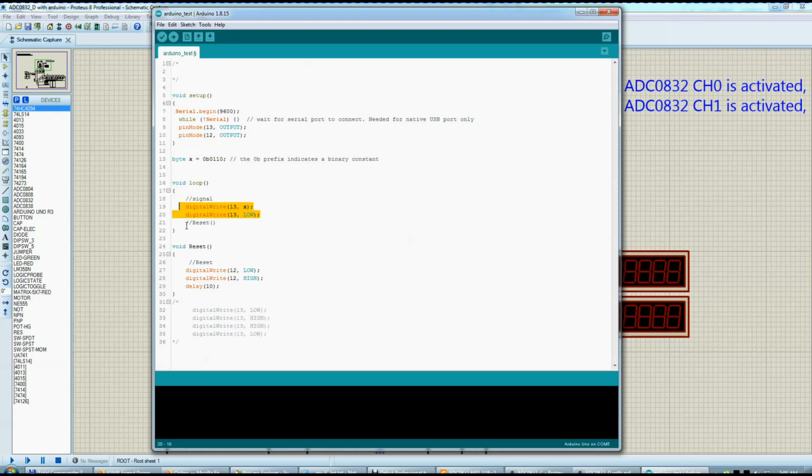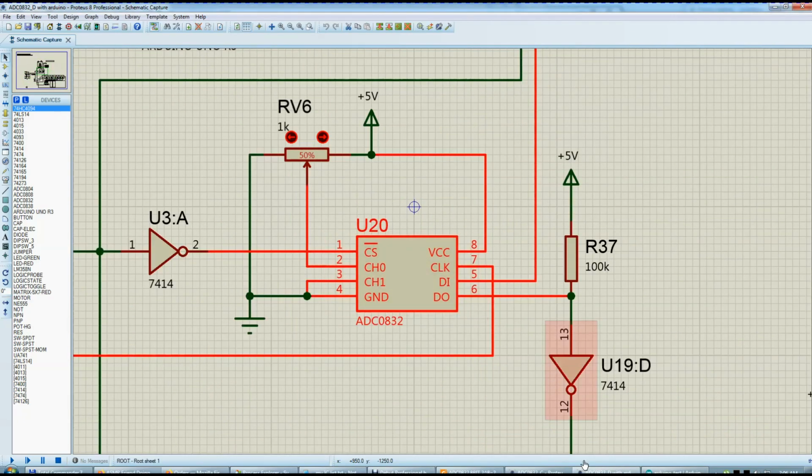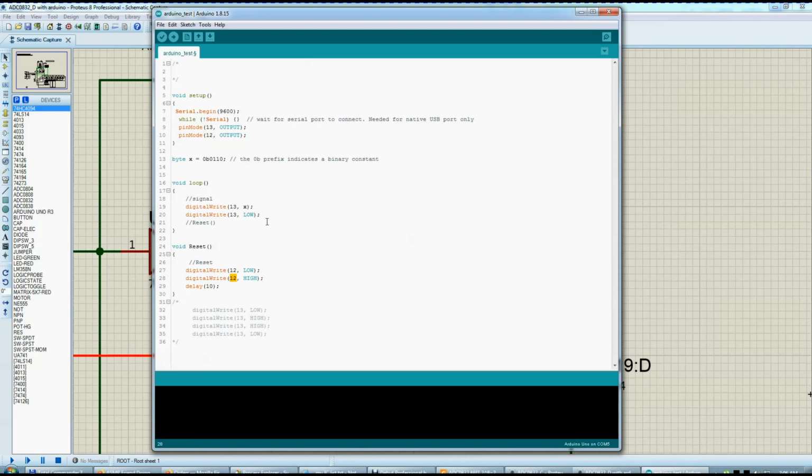Make abstraction of this reset, as you can see, it is commented out, it is not used here, because I was trying the other pins. If you remember, I explained earlier, it is not functioning, it is not working. The ADC doesn't like the clocking and the code in the same loop. I have no idea why.